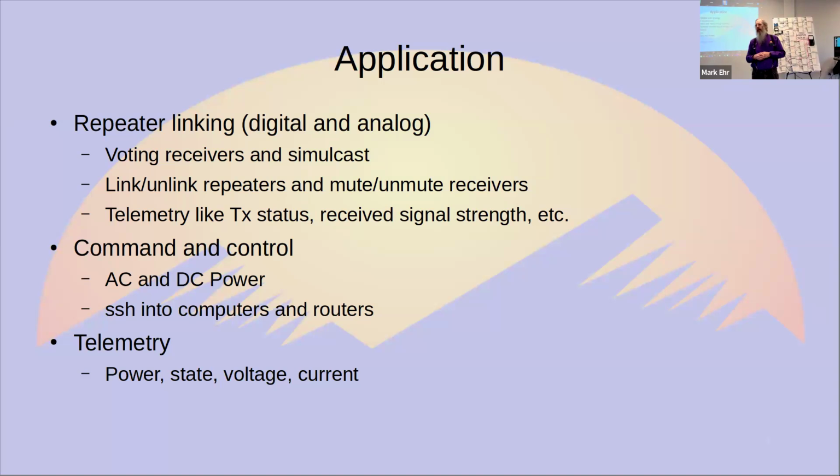There can't be anything in the middle. Even a little bit of trees in the middle will cause all kinds of problems. And in the 60 gigahertz band, it is subject to rain fade. So, of course, in the 60 gigahertz band, we have much more bandwidth per channel, so you can put a lot more through a particular one of the channels.